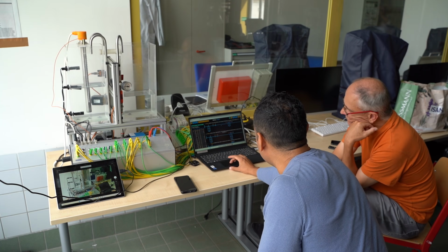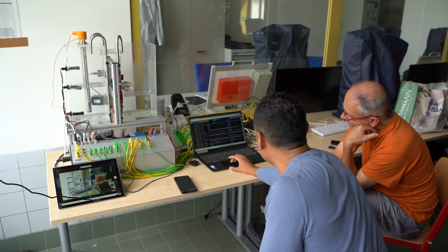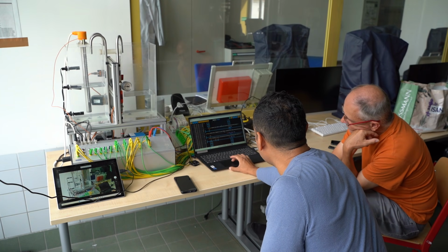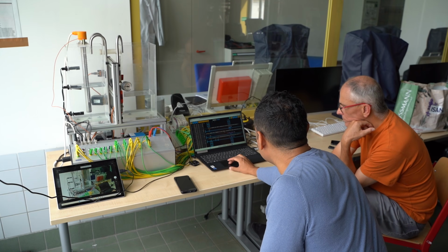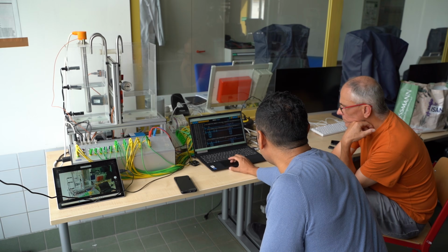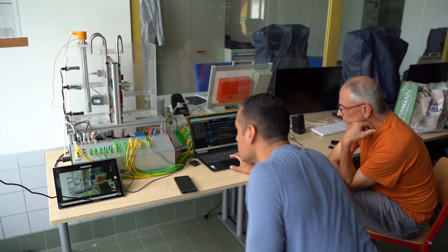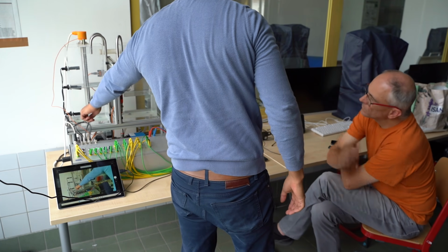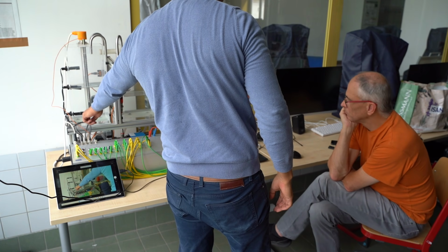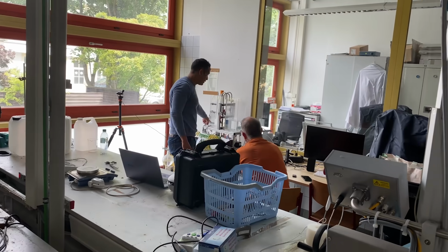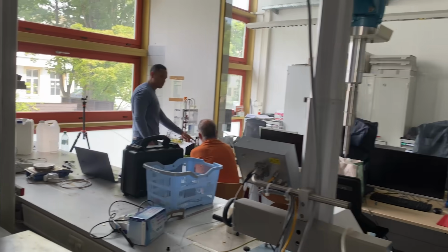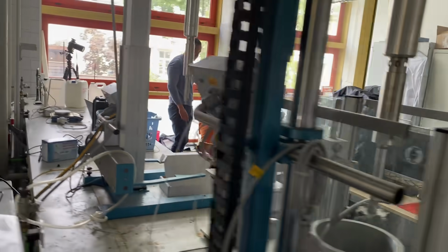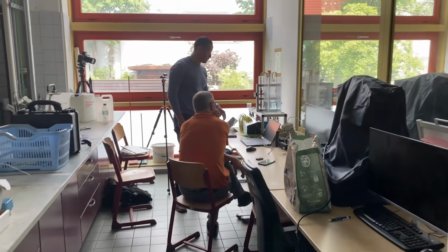So there is one condition for safety that I apply here: the system cannot start unless there is water in the system. At least the sensor, the low level sensor. If there is no water here, the system is not going to start even if you want. As the brain, it will stop it for you.